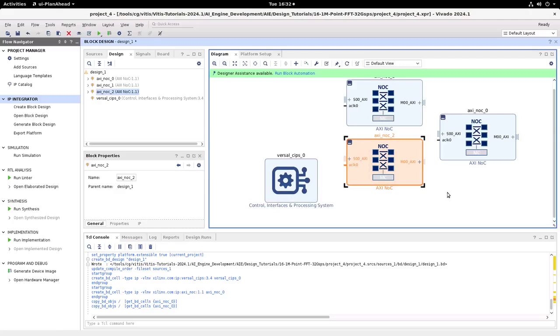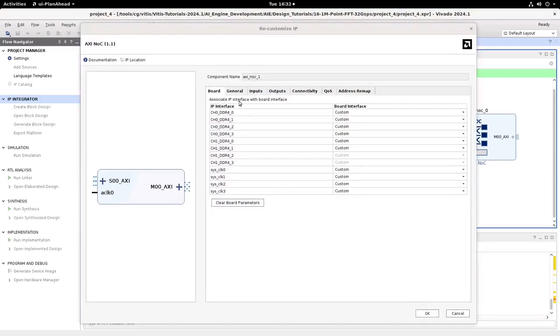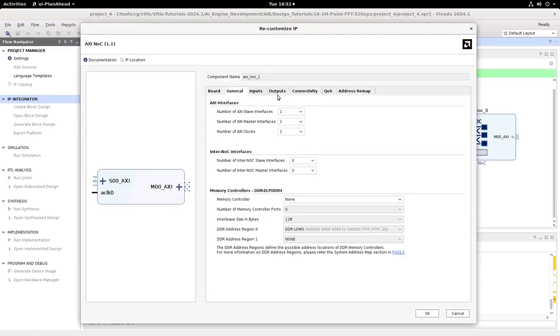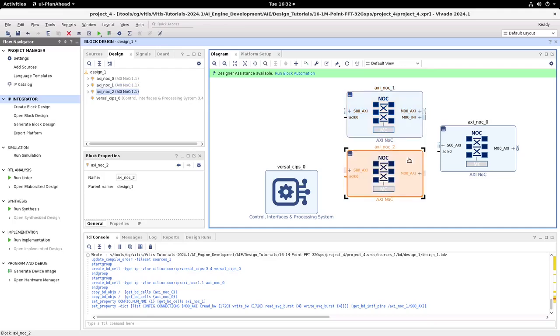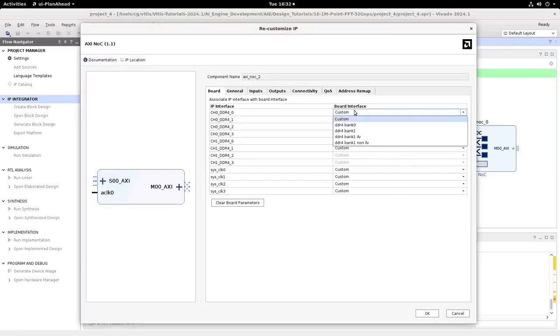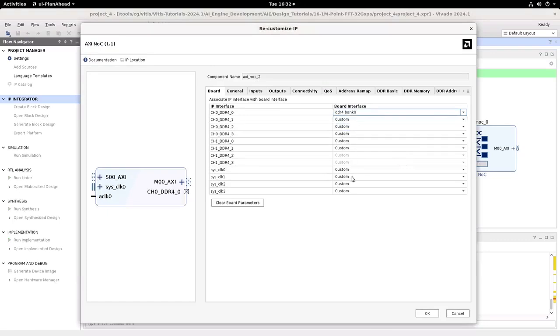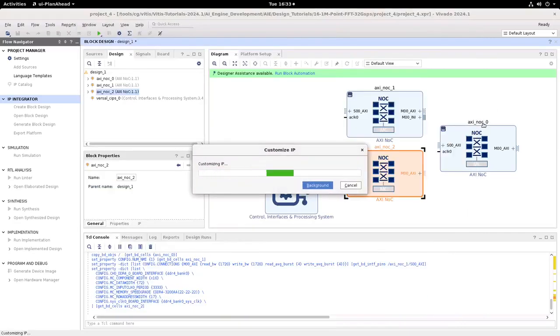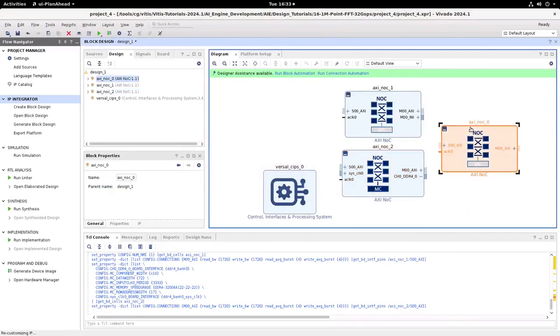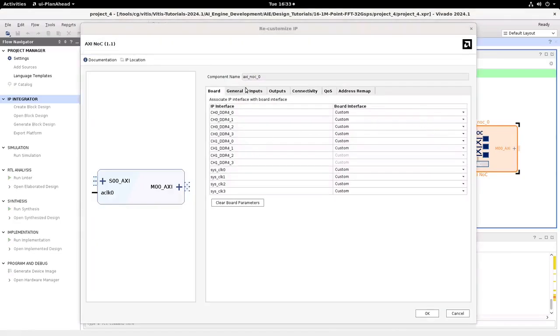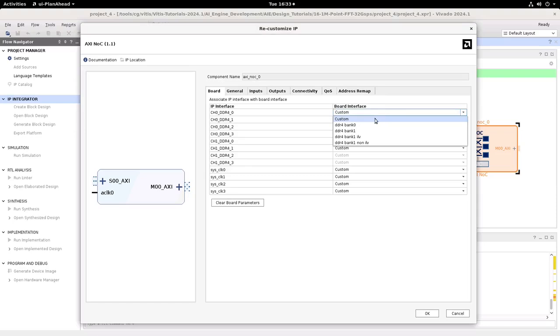Well, this will simplify things, as we'll have one that will be dedicated for routing, and the other two will be dedicated for the DDR controllers. We'll need to select between two bank configurations to match what is implemented in the actual board, so we'll select bank 0 on one DDR and bank 1 on the other DDR.